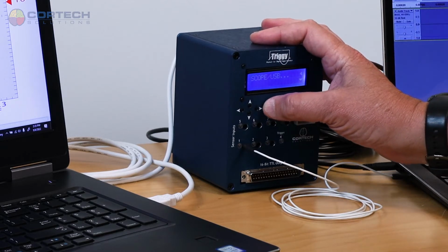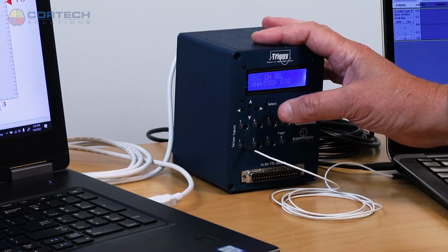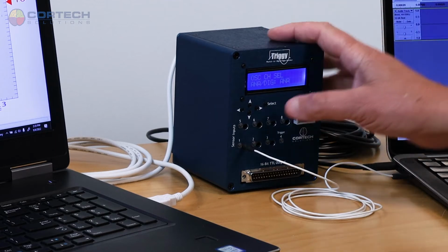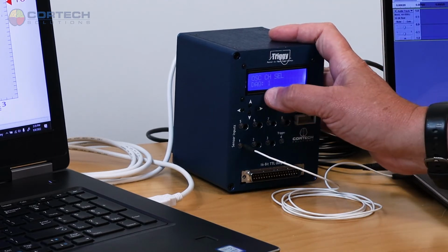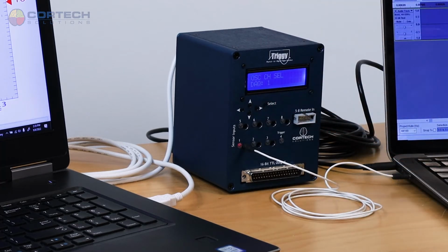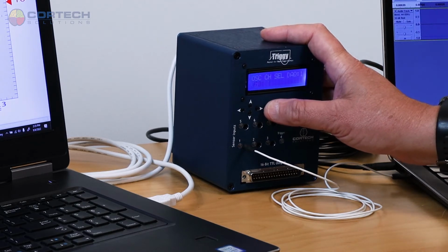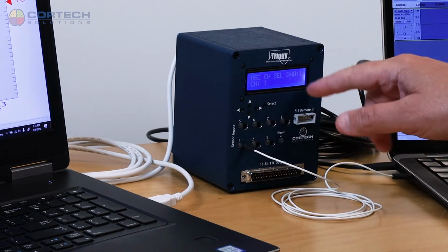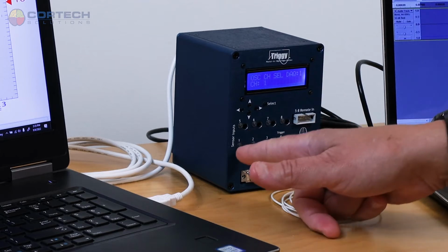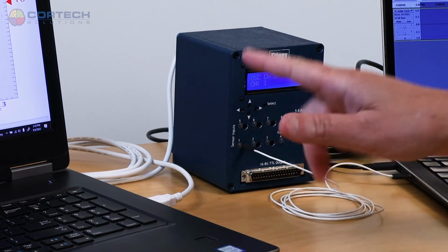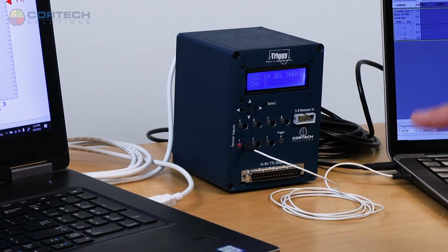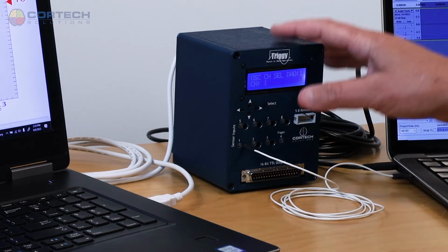Then I'll go through that process again, except this time I'm selecting an analog channel. That's the audio that comes from the sound card. And I'm going to send that to DAQ number 1. So I've assigned to DAQ 0 the digital channel, and for DAQ 1 the analog channel coming from channel 1. Because remember again, the audio is on channel 1 and it has 2 forms, analog and digital. So the first question it asks is which of those I want, and then from which channel to go to which DAQ channel.